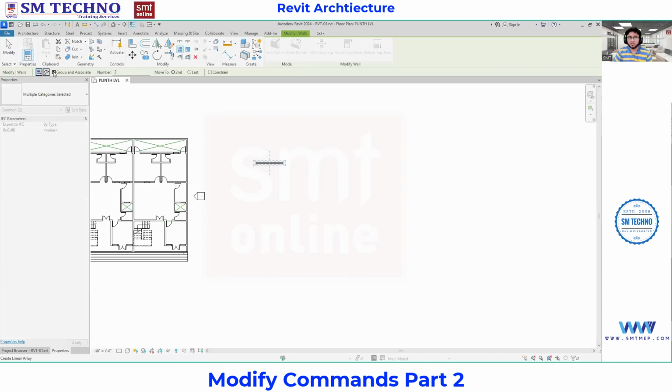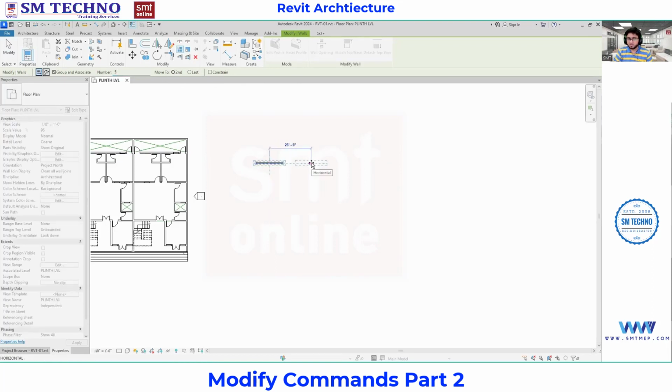In this linear, you can see Group and Associate means when we make an array, it will be in a block, like a group in AutoCAD. Specify the number of quantities, like how many objects you want. Like I need 5 objects. Here we have Move To, second, last or constant. You can keep constant always on because it will move in one direction. I'm going with Move To, second. I'll specify a distance of 25 feet, for example.